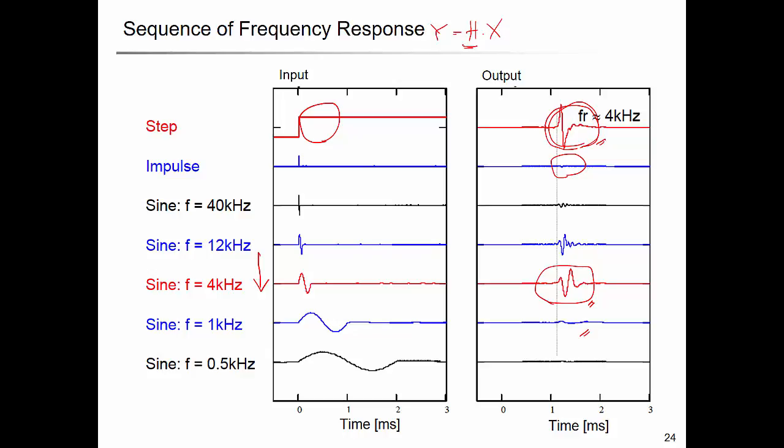Then when you apply the step signal, the movement of this bender element matches with the resonant frequency of the soil. So it could be like 10 kHz. So the arrived signal will be like this for the low confinement, but it's going to change like this with the more sharp edges at the high confinement.